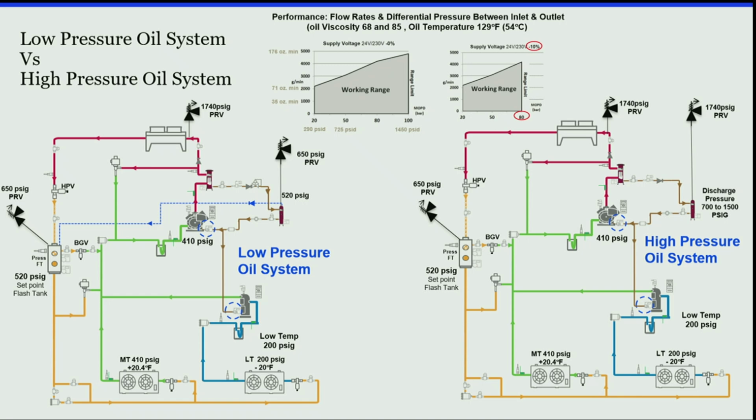Have you ever heard of the OMB? The OMB can be used on medium temp because it's 60 bar rated, much lower, but 60 bar is way above the 45 bar pressure relief on the low side. So if you're ever stuck and can't get an OMC, you can use an OMB as long as you're on a low pressure system, not a high.